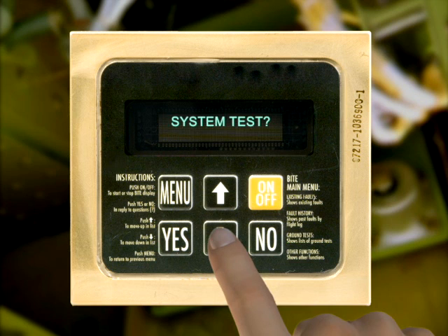Pressing the down arrow takes us to System Test, which will run an operational test of hardware and will operate the system in low and high flow. Note, bleed pressure is required to run this test. Next is the NGS Performance Low Flow Test. Then the NGS Performance High Flow Test. You will also need bleed pressure for these tests. And last is the Display Test.